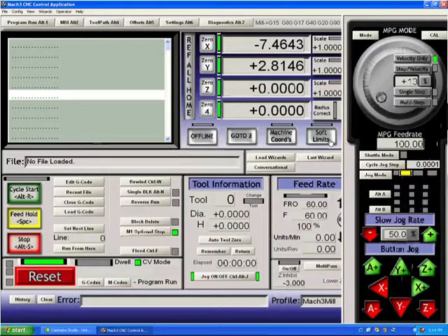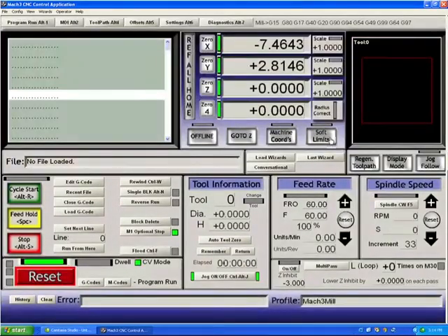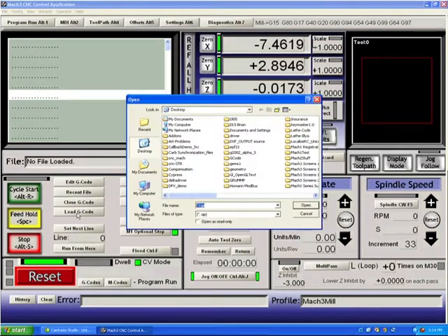Hitting the Tab key will make that jog screen leave the screen. So at this point in the program, I can now jog, my motors are moving, and if you've tuned them properly, you should now have some pretty good movement with them. If you want to do a test to see how your system can respond, we can now just load a G-code file. If you select the Mach3 folder on your system,